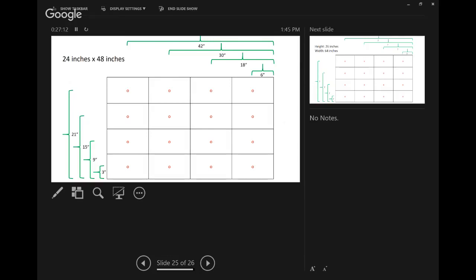One thing we can do, well, we're going to do two things. This probe has measurements on it. We'll measure on the fume hood itself and put a little tiny mark with a pen across the bottom. We'll take our measurements, then move to the next one, and the next one. It's important that we don't get in the way of the face, because that will obstruct the airflow as we're taking the measurements. So we have to try and stay out of the way.